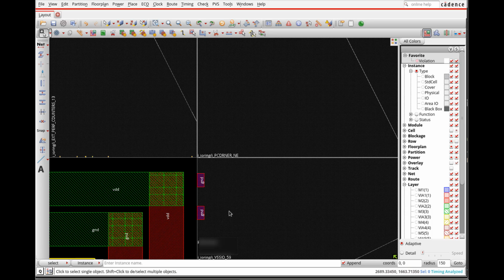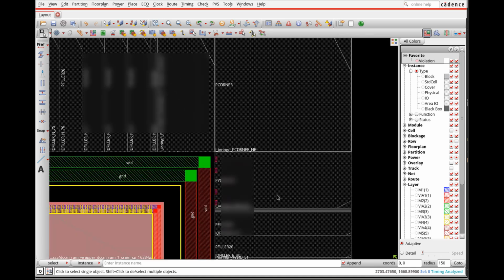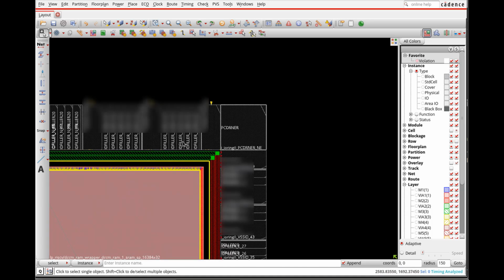Now, you should know that it really depends on where I put these IOs. It could cause all kinds of DRC violations, because, for example, if I want to route this, I'm going to have to keep distance from this VDD array of vias and so forth until I get to the ground pin. But these are things that we really have to play a lot with. Again, I didn't take any thought into where I put the IOs over here. It was really just whatever the spread that the tool gave me. That is not what you are supposed to do. But anyway, so now that I have that, the pad pins are going to connect to these VDD and ground rails, the pad VDD and VSS.